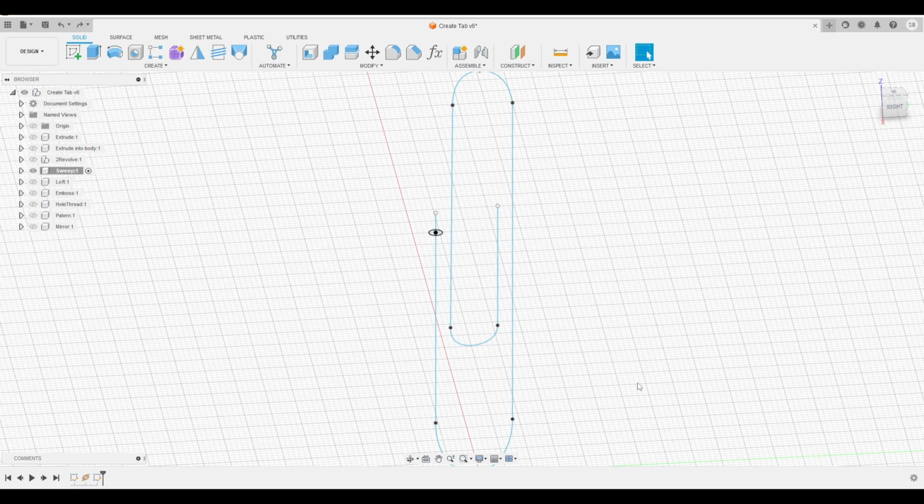What it does is that basically it grabs two sketches. First, a rail sketch, and secondly, a profile sketch. The profile sketch will go through the rail sketch while giving volume. So in this case, I sketched a paperclip, but you can sketch whatever you want to.